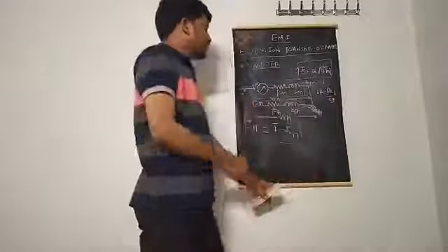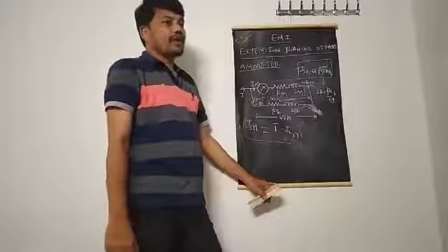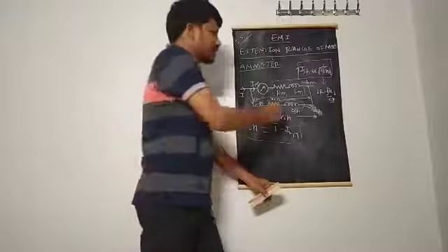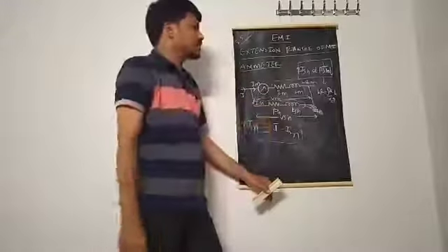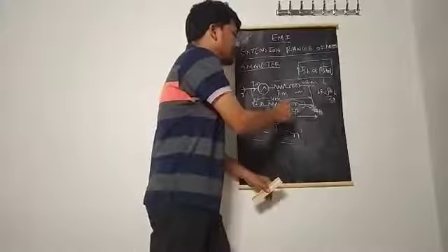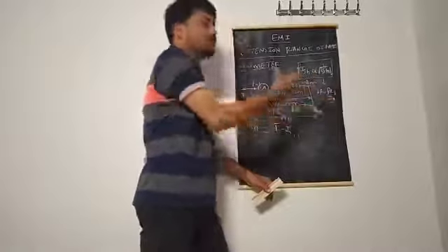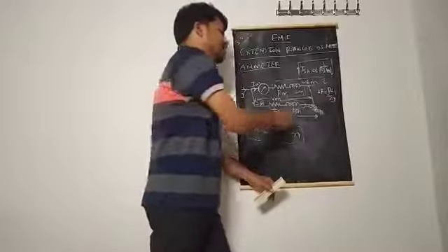In the case of extending the moving iron ammeter, the connected resistance should be low resistance and have a very thick wire, because the area is more, and the length is very small.